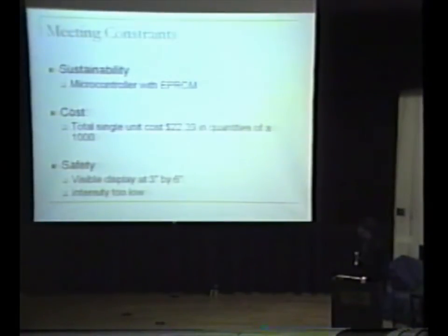Meeting my constraints, sustainability. Using the microcontroller with the EEPROM allows for the system to be updated. All you have to do is burn a new EEPROM. Cost, the total single unit cost for just the display and the driver was $22 in quantities of 1,000. Safety, the display is 3 inches by 6 inches total, which should be significantly large enough to be viewed. However, the intensity is too low, so this will need to be addressed.